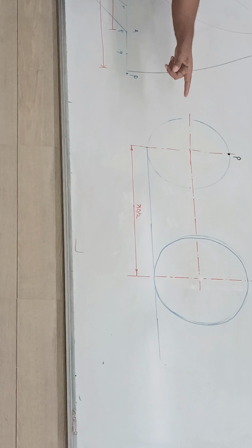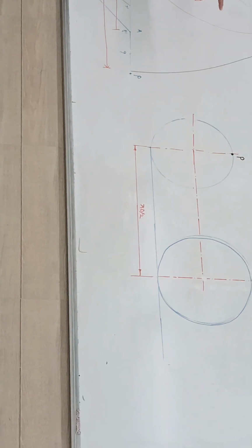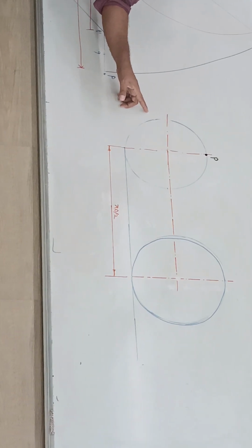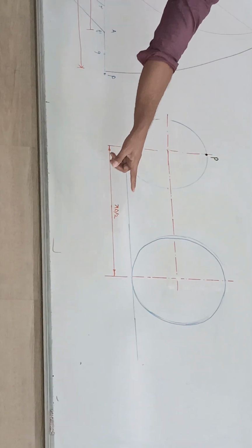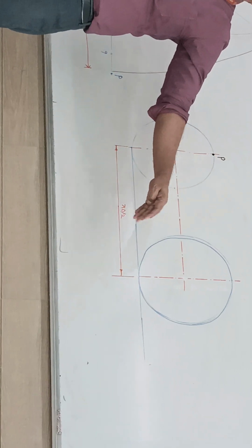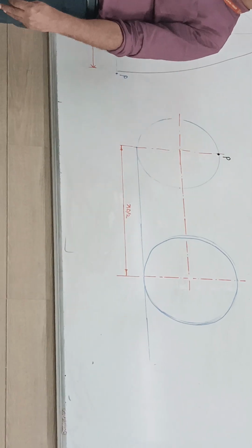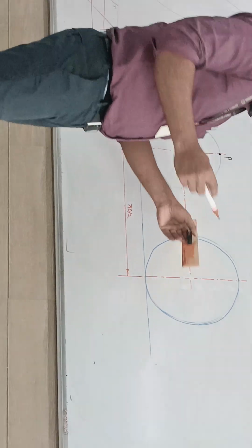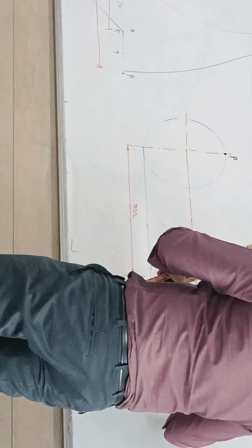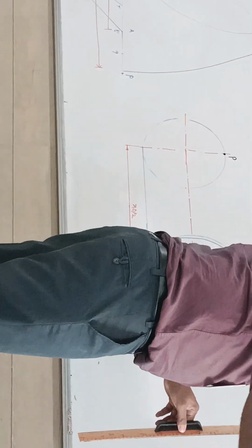Is it clear up to here? Okay, we have to draw circle 1. Diameter of base circle is 50 mm. We have taken the distance pi d by 2. Now this is going to travel half a revolution on the horizontal surface, and half a revolution on the vertical surface. So here there is a wall again, a vertical wall.